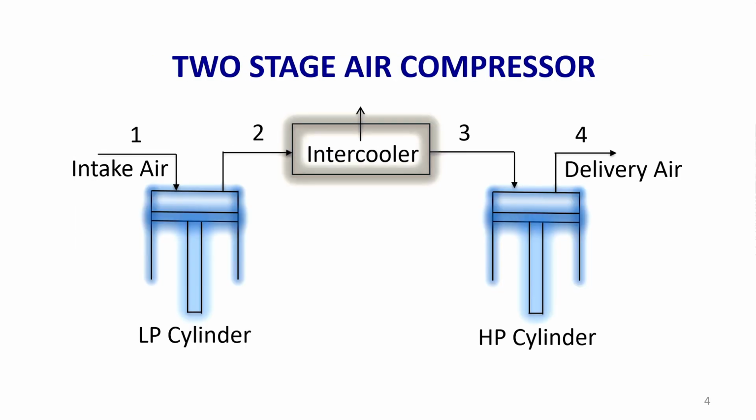So, because of that, what they are doing in the multi-stage compression is, the temperature of the fluid after the compression, after the first stage compression, the substance is cooled by a medium. So, the temperature alone is reduced again before it is compressed in the second stage. So, we will see that one in the construction and the working.